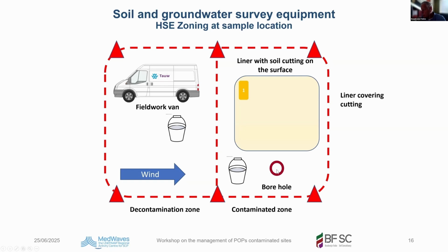So this is your borehole. You take your sample. You put it here. Sample number 2, sample number 3, 4, 5, 6, 7, 8, 9, 10. Make sure that this one is separate from this one, so that no soil particles are being spilled on one another. So you travel with your auger, put here 1, 2, 3, and here you start again.